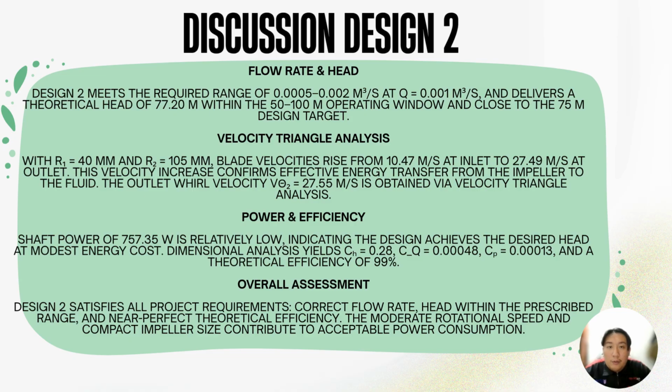And lastly, for the overall assessment, design two satisfies all project requirements: correct flow rate, head within the prescribed range, and near perfect theoretical efficiency. The moderate rotational speed and compact impeller size contribute to the acceptable power consumption.